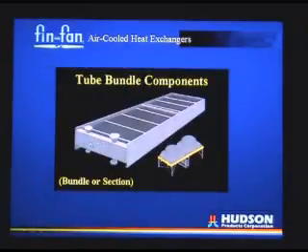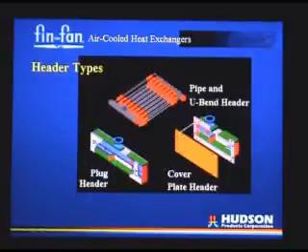This is called a bundle. This is actually a tube bundle where you have a plug header. We'll cover that in more detail in the next slide. This shows you the types of headers that are available. You can either have a full cover plate, you can have a plug header, or you can have a pipe header for high pressure designs. Typically this is what we would use in our industry.